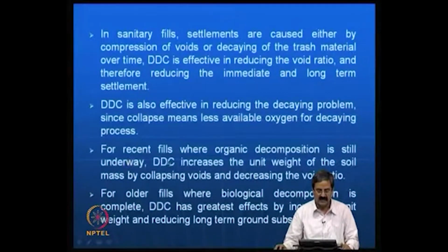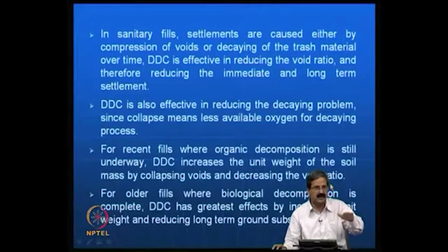Then for some recent fields where organic decomposition is still underway, so it is still going on, the dynamic compaction increases the unit weight of the soil mass by collapsing voids and decreasing the void ratio. Actually it accelerates many things. What it is trying to do is that so much of the settlement it accelerates.